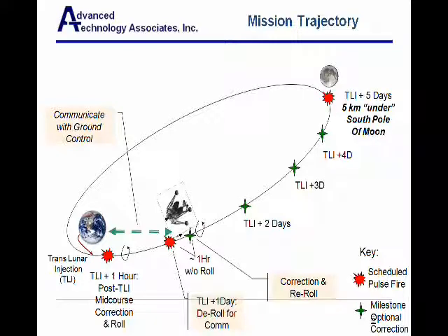The avionics for this class of mission requires a low drift rate IMU. Nonetheless, a stellar star tracker was needed to update the spacecraft's attitude. Ground tracking was used to provide the data to update the vehicle's state vector. The final update of the vehicle's attitude and state vector was scheduled as the vehicle approached the Moon's south pole. The avionics system selected met the requirements that the vehicle touch down within a 5-meter radius of the landing site.